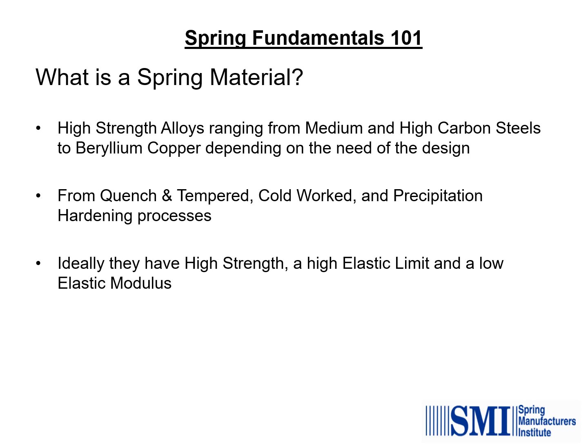What is a spring material? High-strength alloys ranging from medium and high-carbon steels to beryllium copper depending on the need of the design, from quench and tempered, cold worked, and precipitation hardening processes. Ideally, they have high strength, a high elastic limit, and a low elastic modulus.